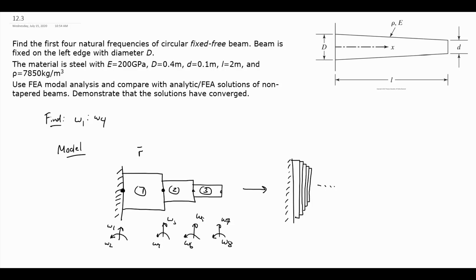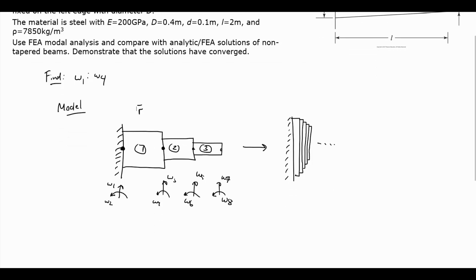But just be aware that how we're defining the constant radius for each of the elements will change how it converges, but in the limit of an infinite number of elements it should not impact what it actually converges to. So determining that mean radius we're going to have to do for each of the elements, as again A and I will change as we go from element 1 to 2 to 3 and so on.